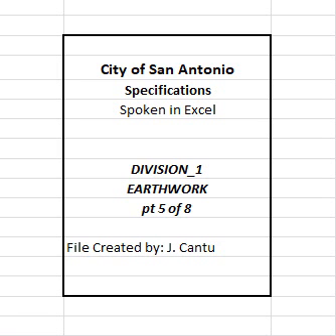When density control is specified, compact each layer to the required density in accordance with section 107(3)d. 2. Density control. When directed, proof roll each rock layer where density testing is not possible, in accordance with TxDOT Item 216, proof rolling, to ensure proper compaction.